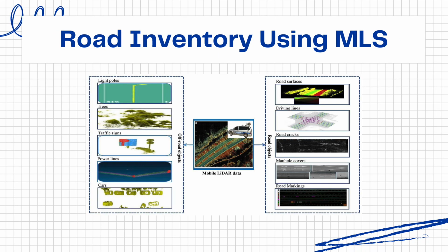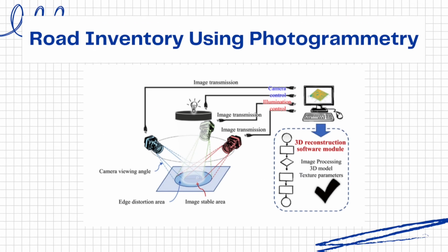In the first case, we use mobile 3D modeling to aid road inventory. Traditionally, issues concerning road conditions are raised by people's manual reports, which means it is time-consuming and not responsive. Therefore, to increase the efficiency, people started to use mobile 3D modeling techniques. Mobile laser scanning technology is installed on operating vehicles, which allows us to achieve reliable inventory management in normal traffic speed. Another approach of photogrammetry is also available and would be cheaper and easier to operate.